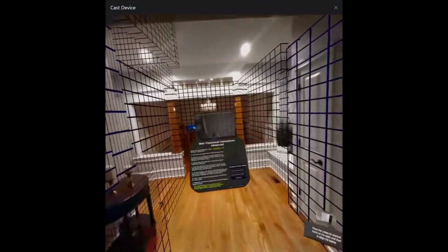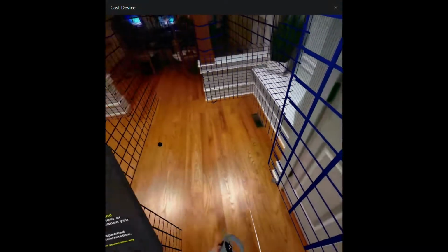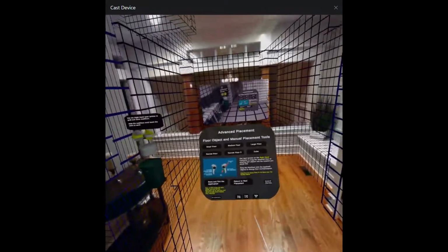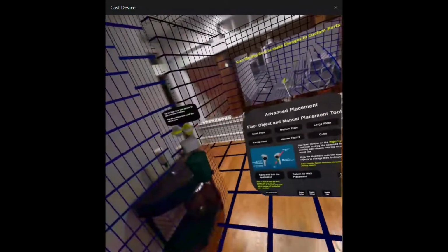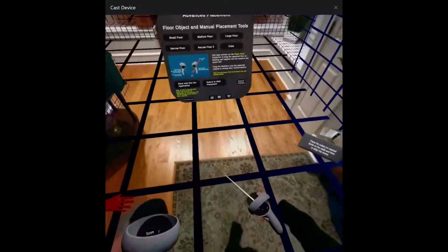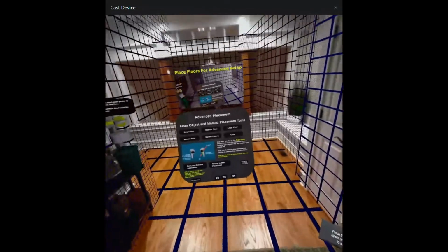Select Continue to Floor Setup to spawn floors. Make sure the white spawn spheres are not intersecting any of the walls, or the walls touching it will get messed up when you spawn the floors. Press the floor button with your left hand and use your right hand bumper and joystick to move the floors to your physical floor. Make sure there are no gaps in the floor.